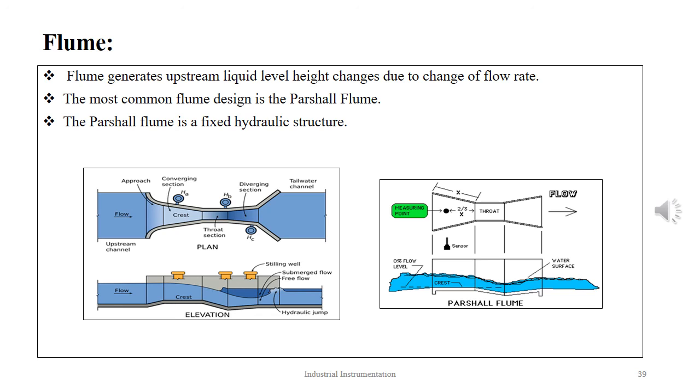The Palmer-Bowlus flume has a trapezoidal throat of uniform cross-section and a length about equal to the diameter of the pipe in which it is installed. It is comparable to a Parshall flume in accuracy and in ability to pass debris without cleaning. A principal advantage is the comparative ease with which it can be installed in existing circular conduits, because a rectangular approach section is not required.